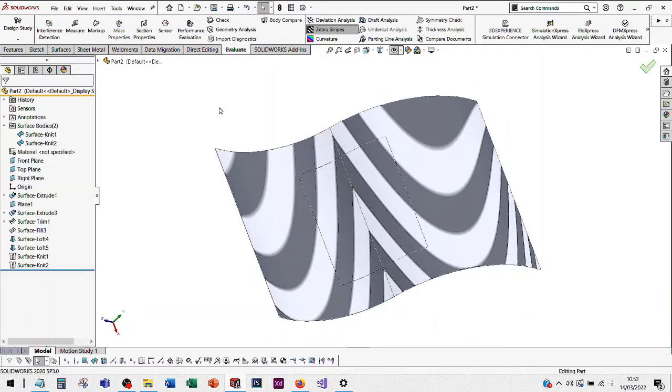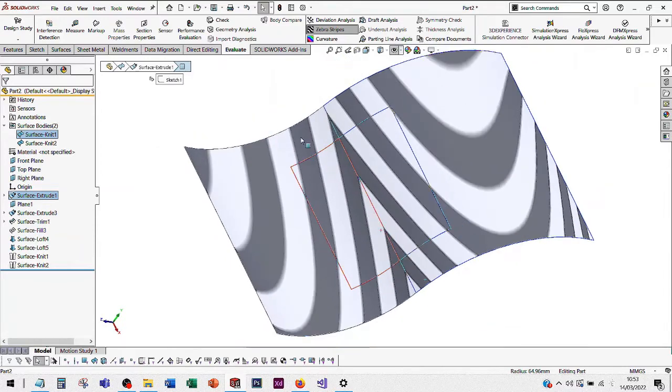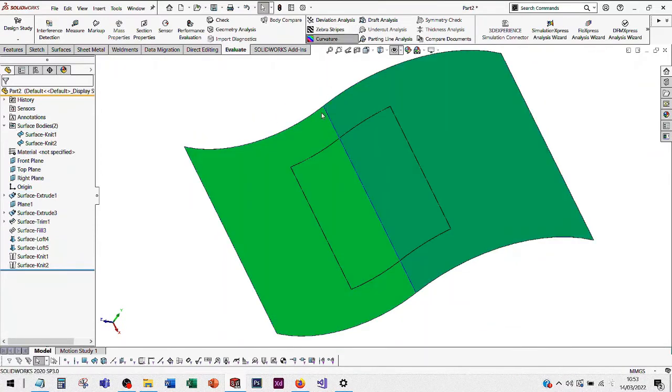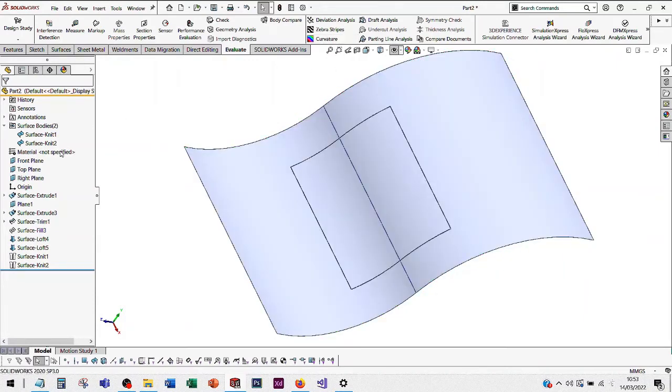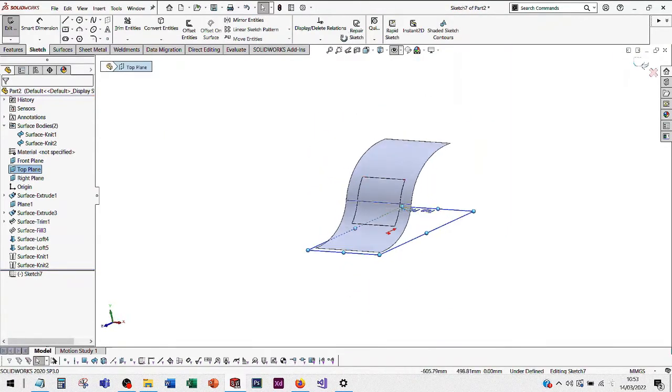So we'd have to cut or trim the surfaces back to create a new bridged surface between the two. So that's the typical workflow you'd be looking to try to create. So we go from this olive green color through to the darker green in a nice smooth transition, rather than this abrupt occurrence here. To do that, we'd have to trim, as I said, trim the surfaces.